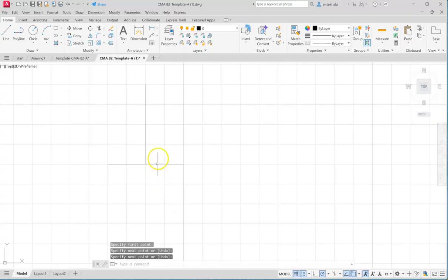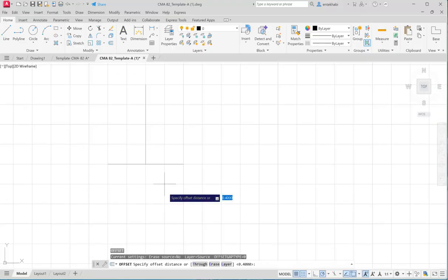Okay. Actually, just making one line would be better, rather than 2 lines. Okay, according to that instruction, there is a 0.05 spacing between each one. I'm going to use the offset. It's the faster way to do that. You could use the array command, but 0.05.